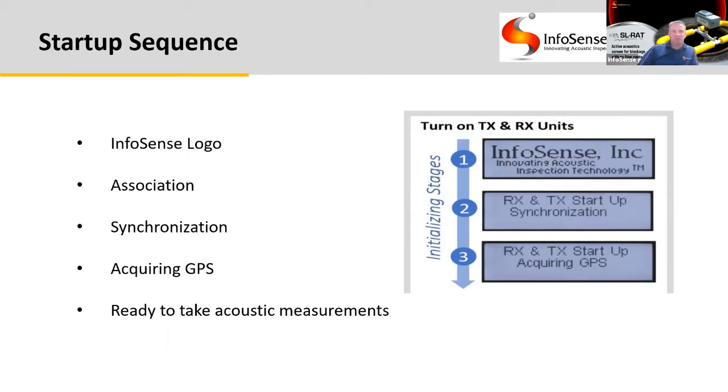The last step in the startup sequence is acquiring GPS. Again, the unit will not move on to a functional state until it locks onto satellites. However, a note to assist when uploading data to your computer: as I've said several times, the startup sequence won't move on to the next step until it completes the current step. Once you get to acquiring GPS, that means the data sync is complete. If all you are trying to do is upload data to your office or work center, then once you see acquiring GPS, you can turn the units off and begin the steps to plug your device into your computer.